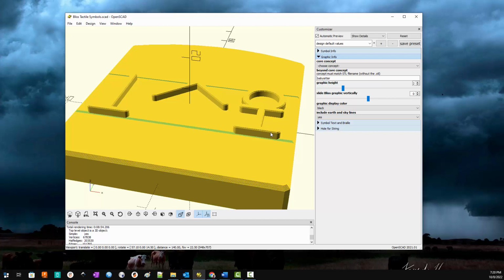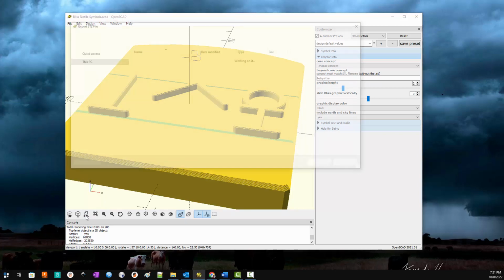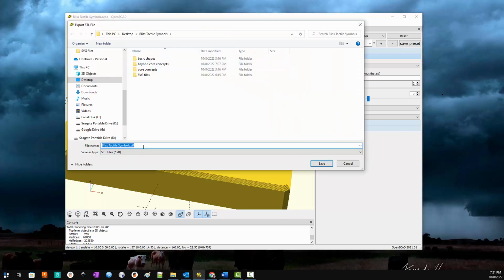So all of this could have been shortcut if I had simply set the chamfering off in the conversion from an SVG to an STL. All of this would have happened very, very quickly as a result, much less than a minute for any one of the renders. So anyway, we've got a symbol now that's ready to print, and we can just save it as an STL file and print it as we normally would any other STL file.